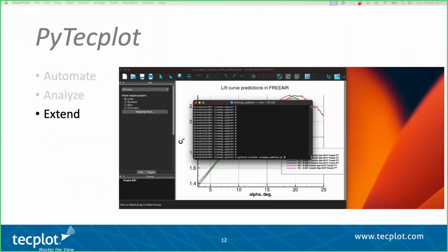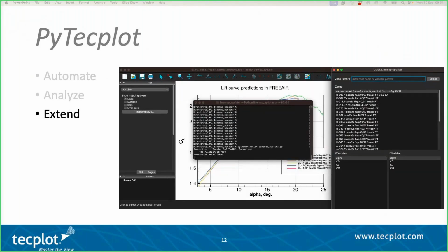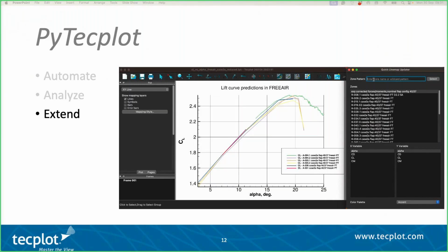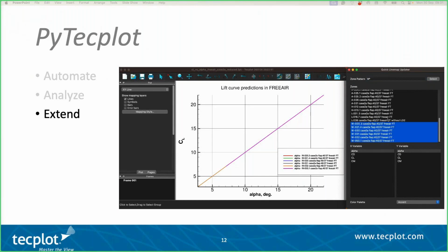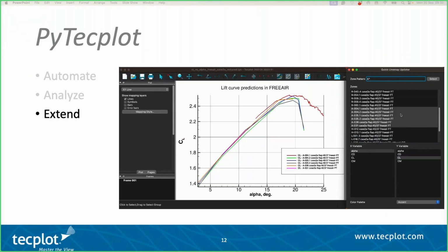And you can also do some nice customizations if you're into Qt coding. PyQt is available. You can create your own panel. So I mentioned very nice 2D and XY plots in Tecplot. And here the idea is that the few settings that are going to be used all the time by this researcher are captured in this simpler GUI. And then it's just changing the input data and the X and Y variables and customizing the two plots very easily. And as I mentioned, this can go out into a vector export for great quality into your publication.